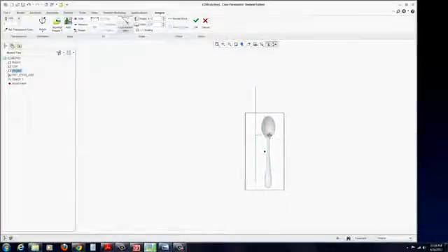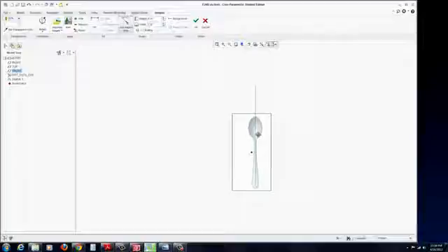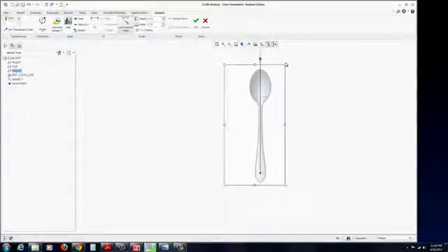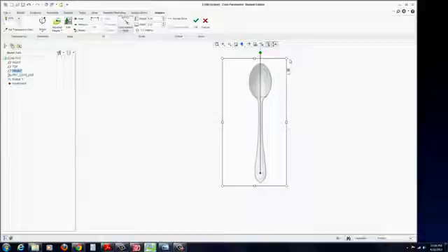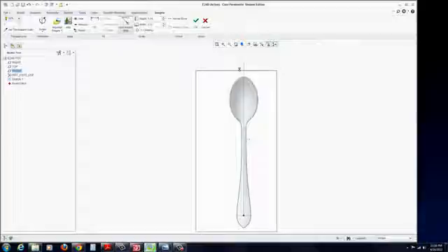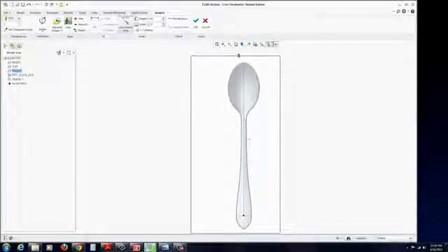You can see it drops in, and we can see our line that we used for the scale. In this case, I want to get this line where it's centered, and then also on that little edge there is a tangent edge. You could grab this dot, which is really helpful. You can put it right on that point. And now if you scale it, you should be able to scale it to that line without any sort of movement or transition. Okay, that's it. Hit OK.